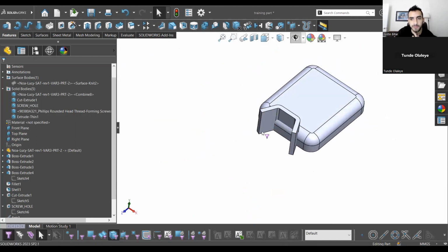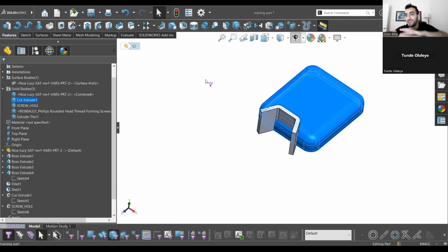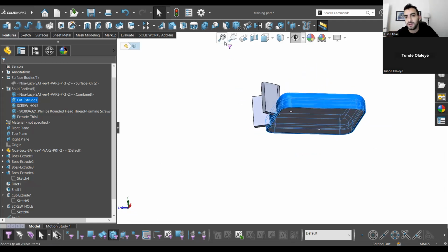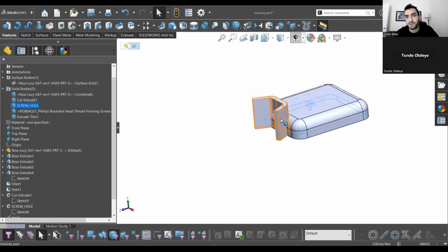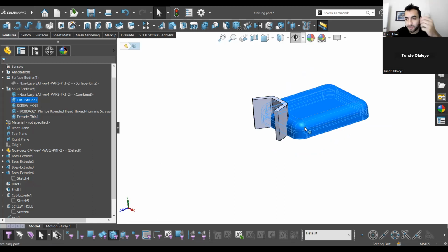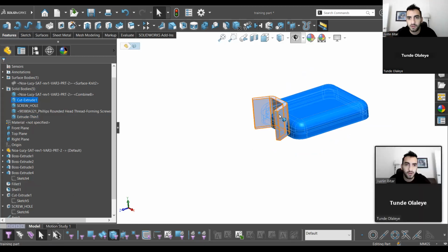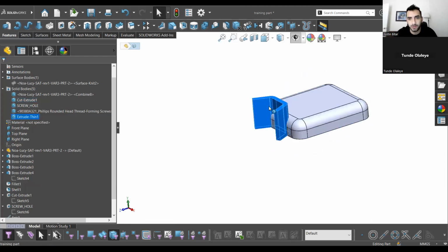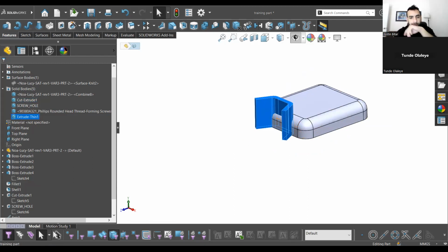So this is its own, okay, so selection filter, right? This is why I have the selection filter here. Filter solid bodies. So now when I click on anything, it'll just highlight that entire solid body, which is really handy sometimes. Because sometimes I just want to say, hey, did this feature accidentally get merged with this? Sometimes I forget to unmerge or merge results or whatever. So this is a quick little tool for figuring that out. And it looks like, yeah, that's its own solid body.